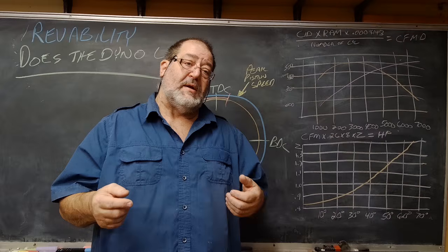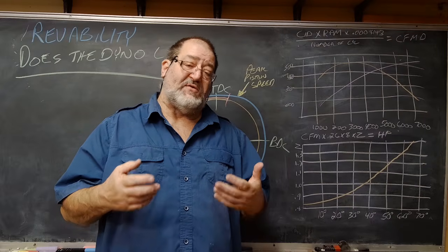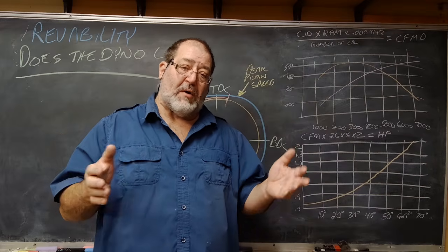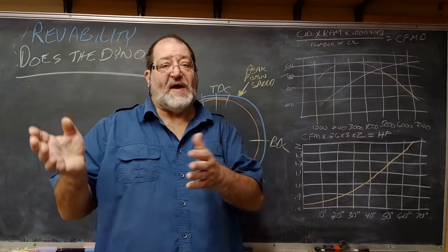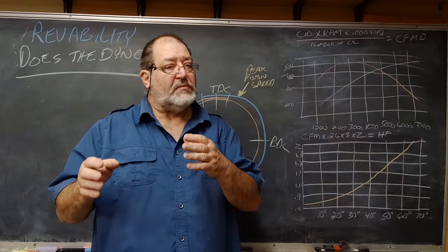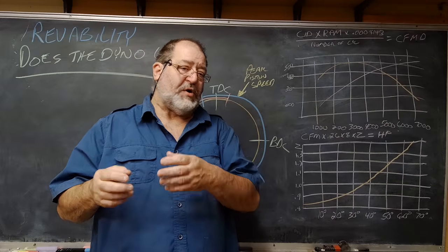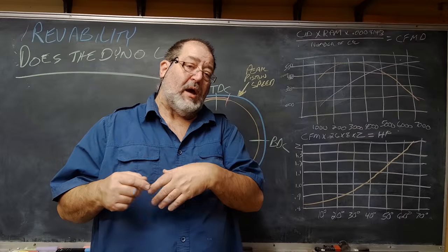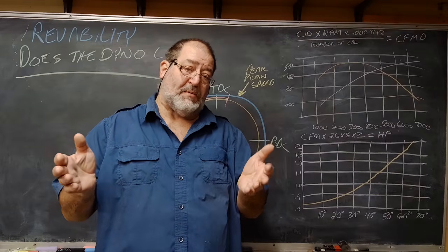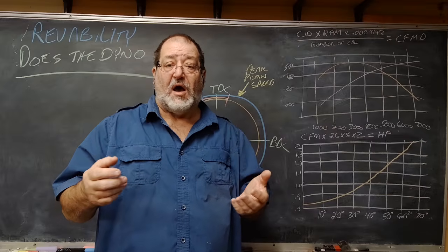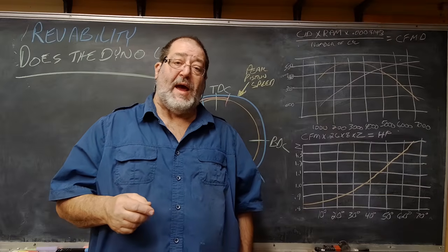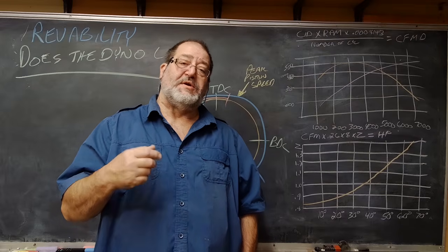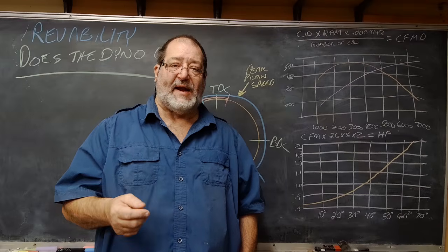The engine, especially on the street, needs to be flexible, and you need to have a slightly decent power band. 3,000 RPM is minimal. If you're down to 2,000 RPM of workable, that's getting kind of peaky. Most engines, you should be able to get a fairly decent band of about 4,000 RPM. And in most of this series, I've talked about that: watching your overlap, watching some of your events in order to help that out.